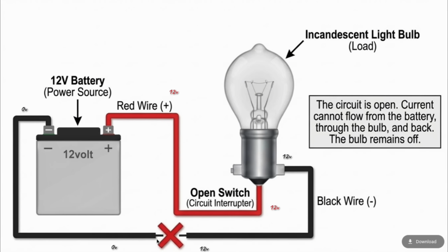Past the break, as I said, everything will drop back to 0 volts because that side is physically connected to the battery negative, whereas this side's connected, there is no negative. It's not connected to the chassis ground at all, is it? Because you don't have one. In reality, it would have some chassis ground, it wouldn't go direct at battery, but still, either way, if it's broke, it's broke. Job done, you've no ground.